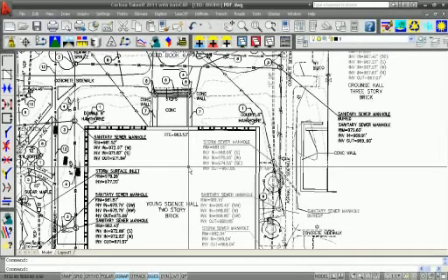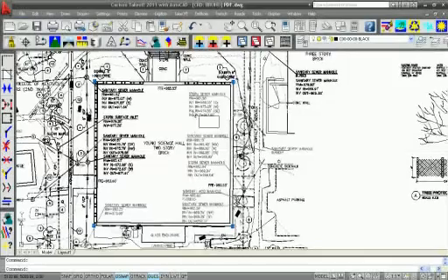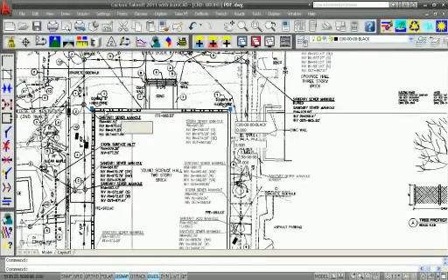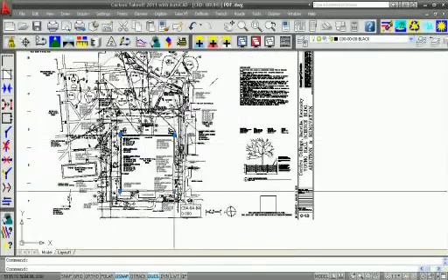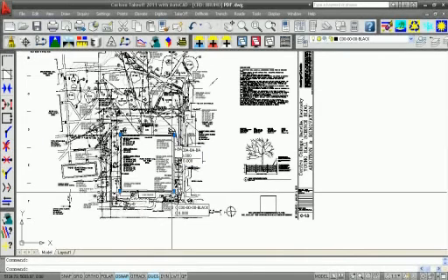But that's based on the fact that we've got elevations in this file. Not on this PDF. You're not getting any elevations. You'll never get an elevation from a PDF file. Okay. But it saves the time of having to trace over the line work. Because what we have in this drawing here is actual lines. Like, if I click on this line here, you can see little points highlight on it. I'm getting a line. I'm not having to retrace that line in, and this is a perfect square. I'm not having to trace that in by digitizing.